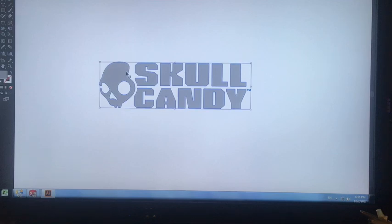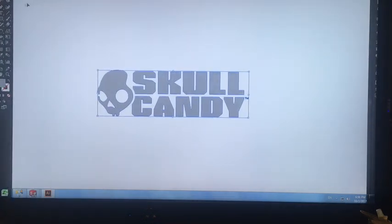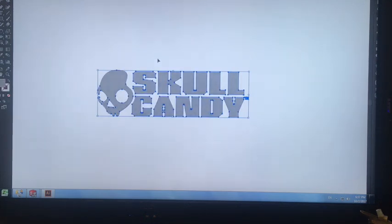So I download the file, and when I select it, once it's opened up, you can see the line work highlighted with that blue. In Illustrator, we have the menu at the top, tools on the side. The V key will get your arrow selection tool up. And here you have your fill and line color or stroke. You can flick those by hitting Shift X while you've got something selected. So if you've got an image and you hit Shift X and you can see the line work or the fill switch to the stroke, then you know that that's a vector image that you can use in SolidWorks.